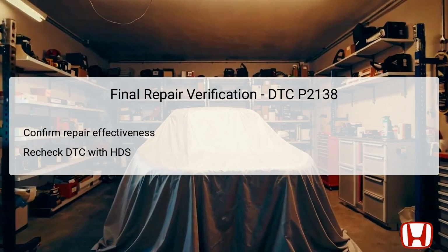Once repairs have been made based on the identified issues, it's essential to perform a final verification to ensure that the problem is resolved. Start by confirming the effectiveness of any repairs conducted, which may involve rechecking connectors, sensors, or wiring as necessary. After confirming each component is in good working order, recheck for any DTCs using the Honda Diagnostic System, HDS.